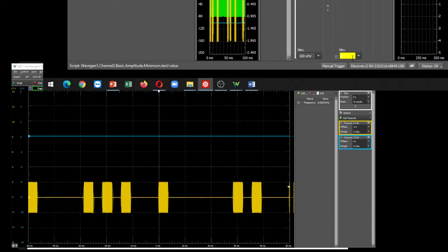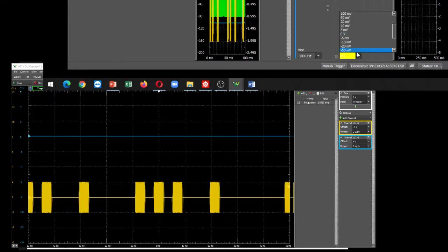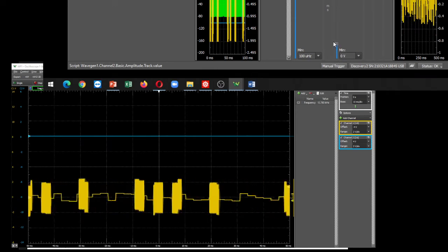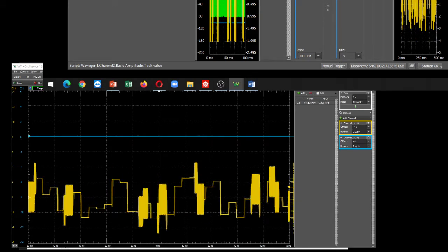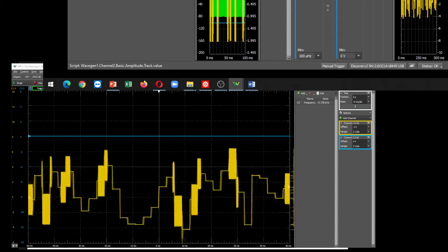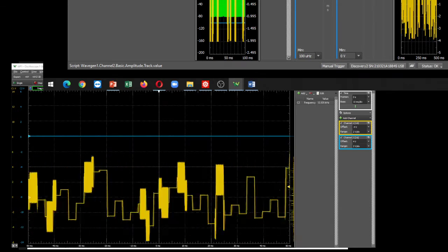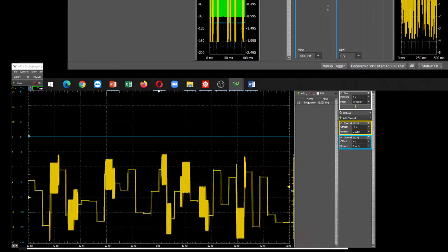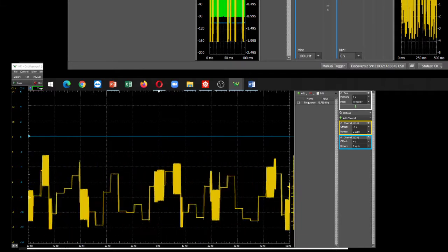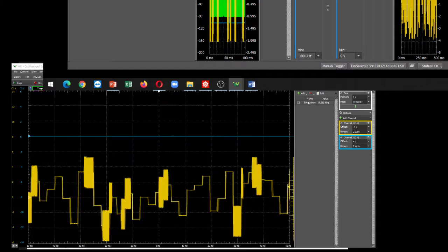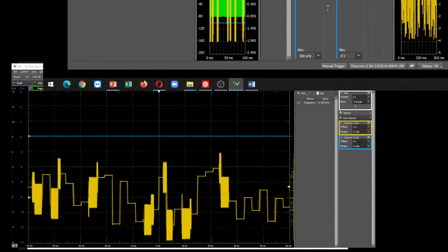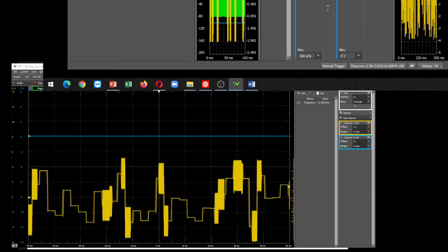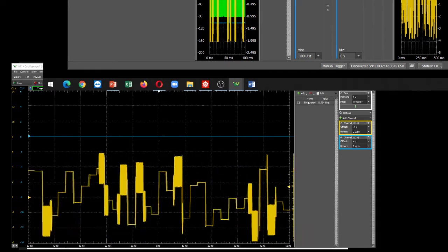Now, let's see the signal with carrier in the presence of noise. Although the signal plus noise still appears to vary widely in amplitude, any part with carrier high-frequency oscillation clearly stands out and is recognizable. The next task is to build a circuit that can filter out the portion with carrier oscillation, the fuzzy part of the signal as seen on the scope, and reject the rest. The type of circuit that can do this is called a filter, or more precisely, a frequency filter, or spectral filter.